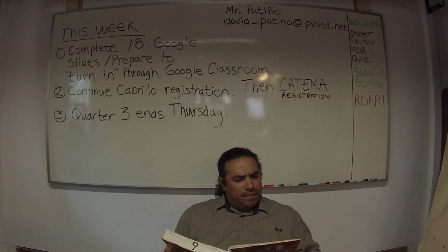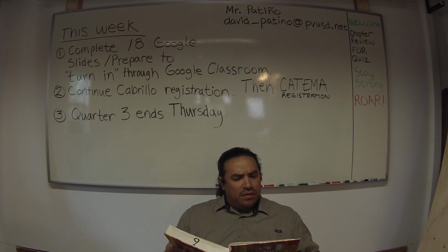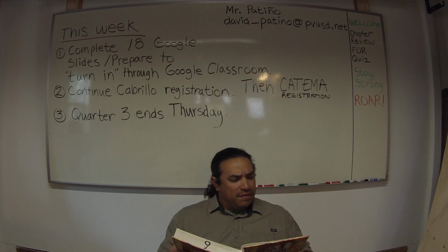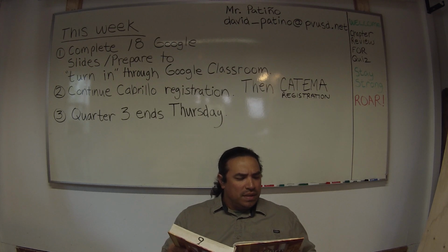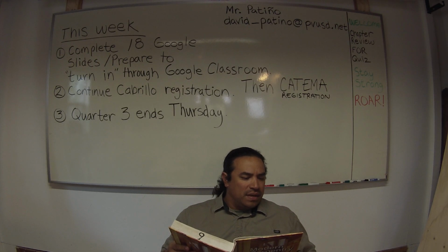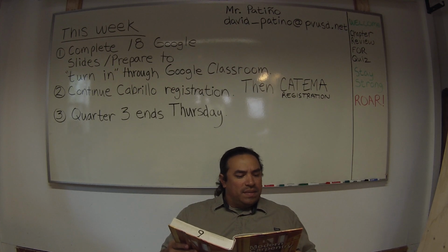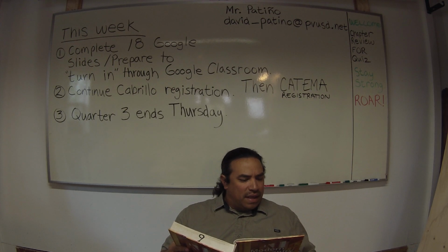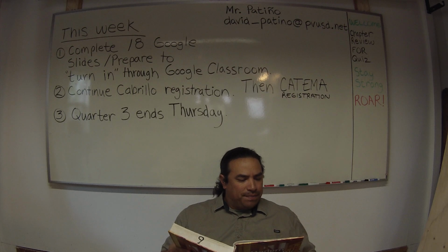Cutting methods. Most lumber is cut so that the annual rings form an angle of less than 45 degrees with the surface of the board. This produces lumber called flat-grained if it is softwood, or plain sawed if it is hardwood. This method produces the least waste and the most desirable grain patterns.